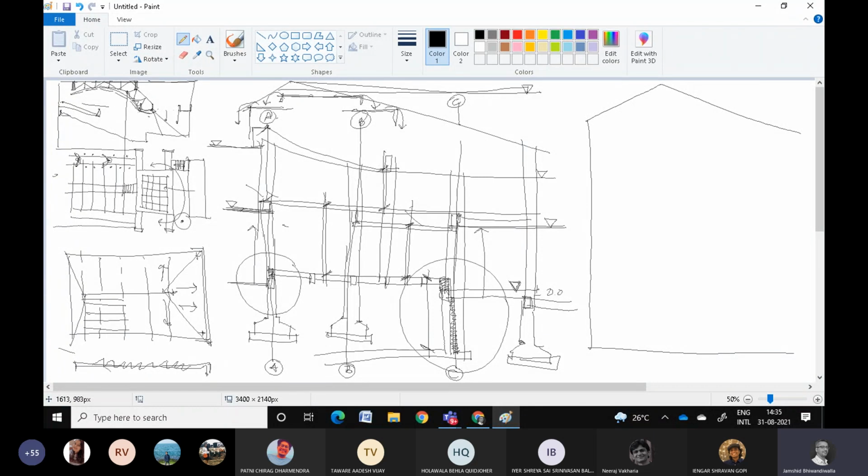Columns shown in elevation always help the person understand at what level and at what distances the columns are. The columns also help you to state the center line and things like that. So what you're saying is that it is not necessary that all aspects of the section need to be seen. Sometimes if you draw everything, it may become too confusing. Yes, but show things that are structurally relevant in the section, preferably in close distance to where the section is cut.